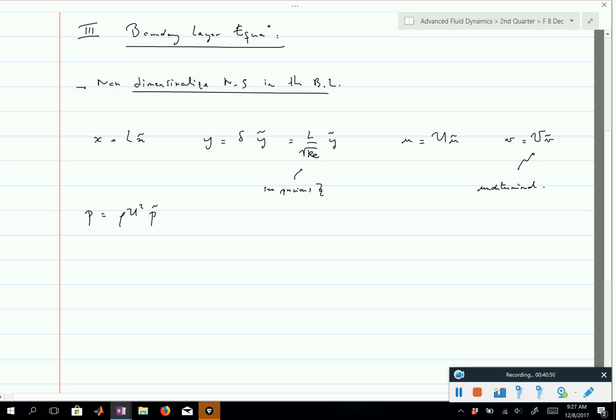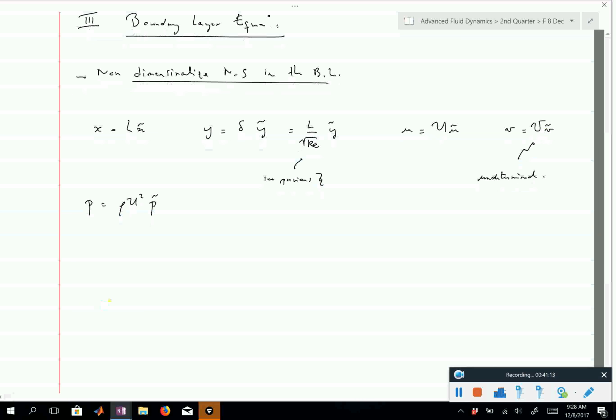Right? You know that if you look at the equation for continuity in 2D, it's partial U over partial X, partial V over partial Y. This is just another way of saying that mass is conserved. Whatever change in velocity in the x direction you have creates a change, like an additional or not enough mass that needs to leak then through the other direction, right?